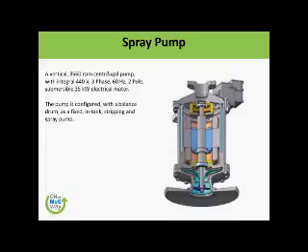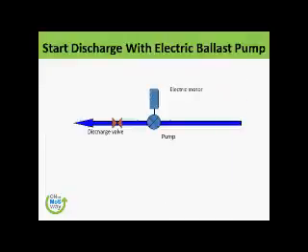This is the junction box where the cables come and connect to these pumps inside the tank. So technically, these pumps are always submerged in the liquid when the tank is loaded. So the start of ballast is just a start of electric pump and discharge. Why we are showing you here that discharge valve in these pumps: if you keep the discharge valve open and you start the pump, it is going to trip.